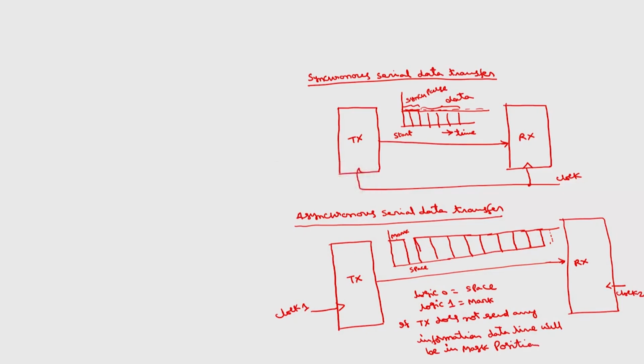This is not yet transmitted, and this particular low bit or space bit represents the start pulse. This is of 1 clock period duration.